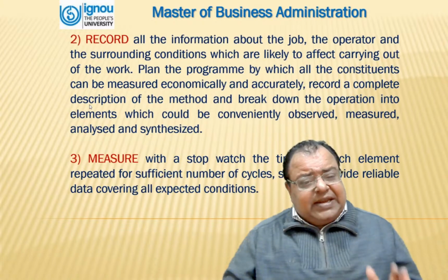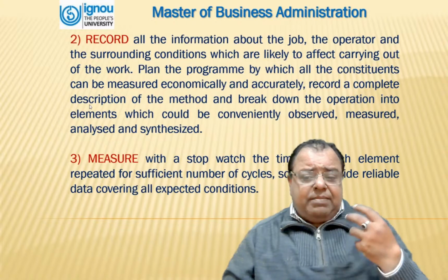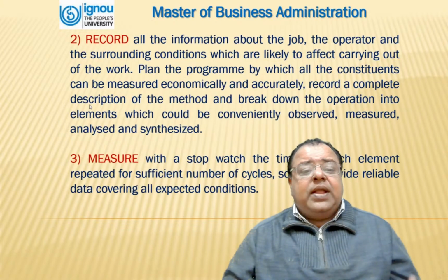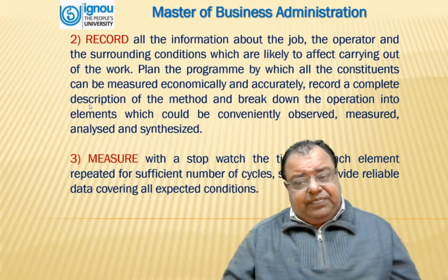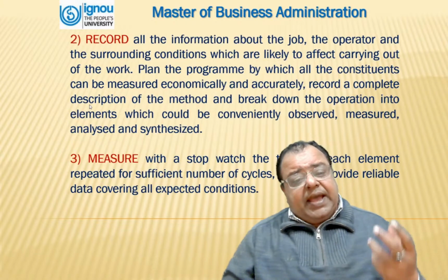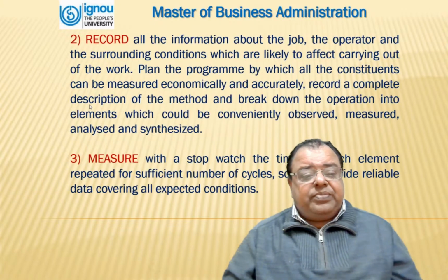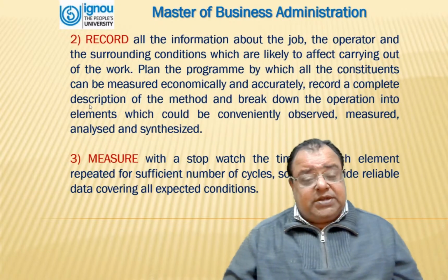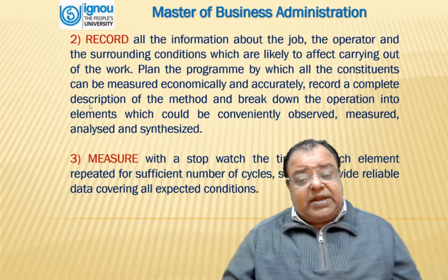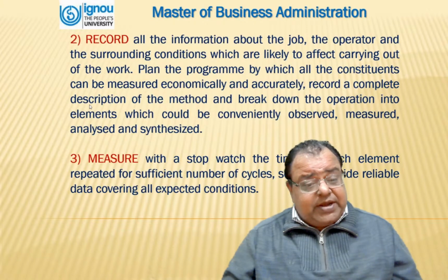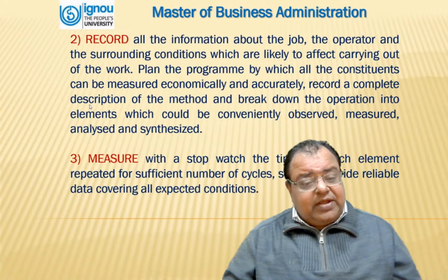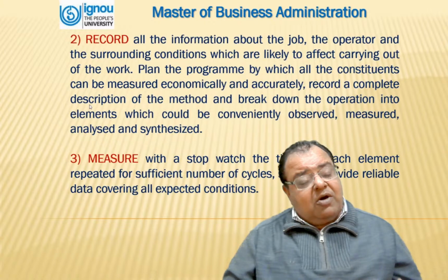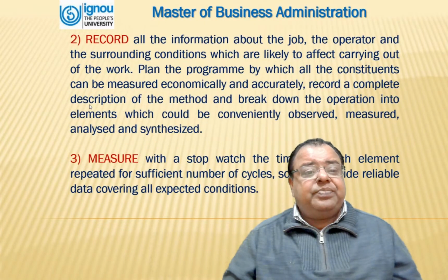Record a complete description of the methods and break down the operation into elements which can be conveniently observed, measured, analyzed, and synthesized. Third, measure with a stopwatch the time for each element, repeated for a sufficient number of cycles so as to provide reliable data covering all expected conditions.